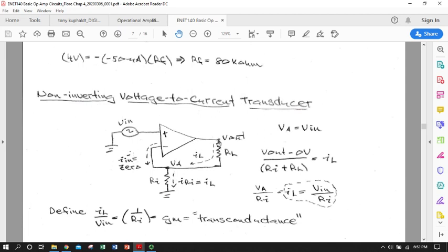We go from V out and we kind of run a test current through it. It's going to flow through the load to V sub A and is not going to flow up here because this has infinite input impedance, so there's no current through this branch. So I sub L must flow in its entirety from V sub A through R sub I to ground. So R sub I and R sub L, or the load resistor, are in series. So V out is just I sub L times R sub L plus R sub I. Not too bad.